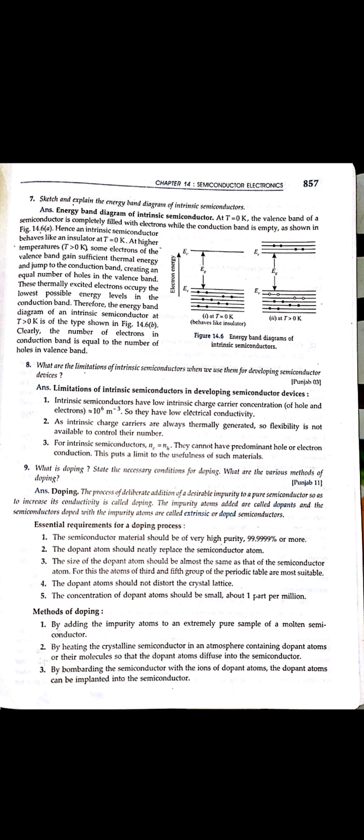To increase them, we add some impurities which should be permanent, so that the electrons cannot easily eject out from anywhere. On adding impurities, we require two kinds: one is pentavalent, the other is trivalent. When we add a pentavalent impurity to the pure semiconductor, it is considered an n-type semiconductor. N is for negative, because when we add a pentavalent impurity, we give an extra electron to the element. As the number of electrons increases, the negative charge increases, so it is a negatively charged semiconductor, named the n-type semiconductor.